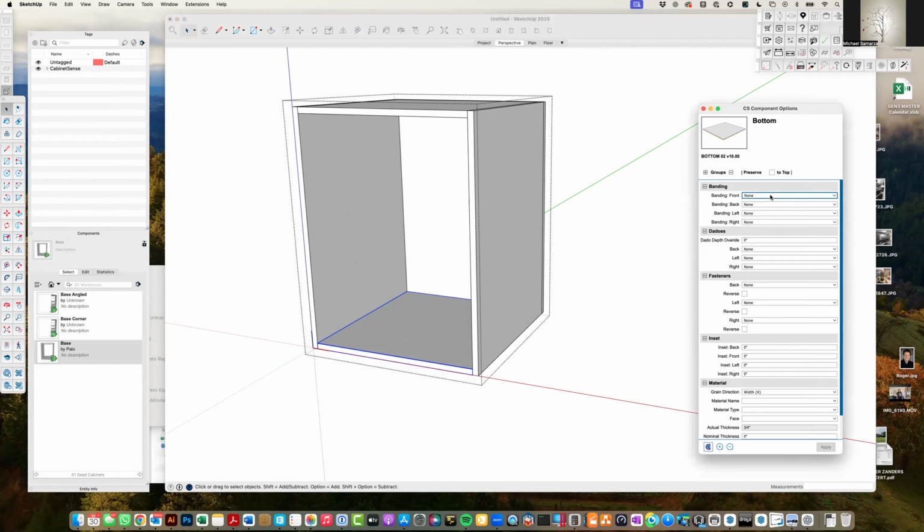All right, so then I'm going to put banding on the front of this because I'm assuming you are doing banding, Euro style. I'm going to do semi-exposed banding. On the left, I'm going to add a dado, and on the right, I'm going to use a dado. I'm glad I put that 1/4 inch in as our default. We can change dados. You see, we have an override if we need to, but we don't because we already specified that our dados are 1/4 inch deep.